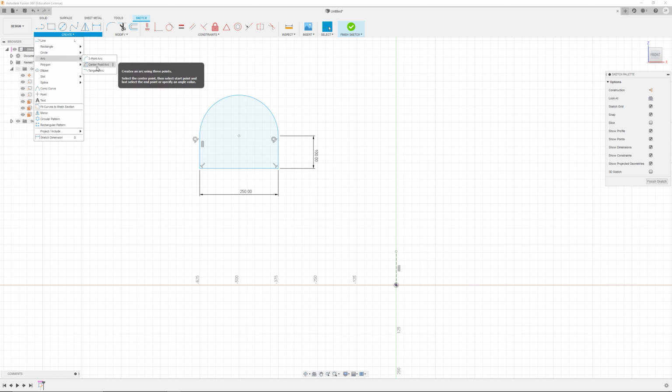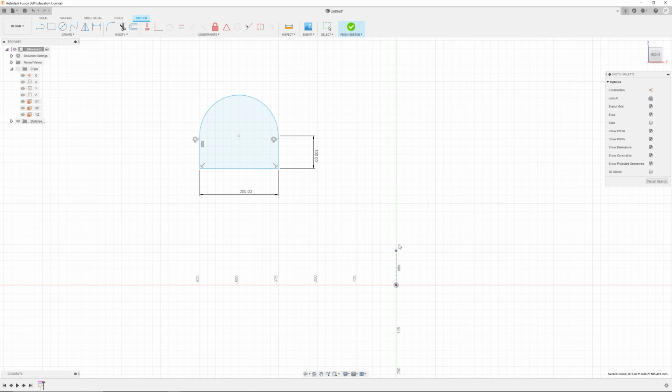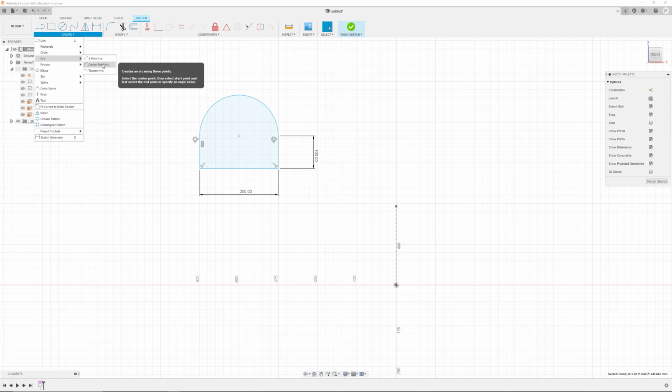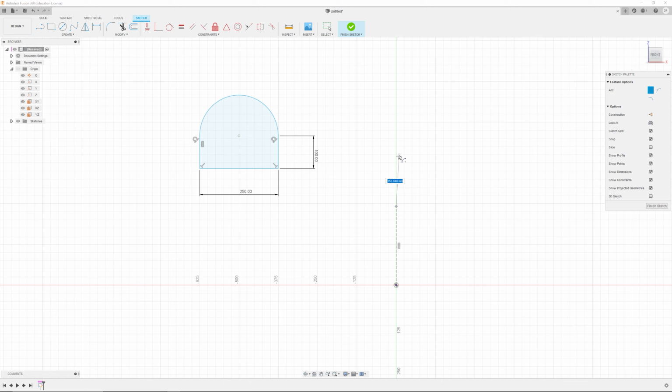And then a center point would be in the case of, let's say I had something like this, where I know the center line and I know where that center point is located. I can create the arc based on where the center of it is, then pick a start point of the arc. So I'm going to start to the left, and then I can draw however much of the arc I need. So it might only be 90, or in this case 87.6, because I didn't draw a straight line.